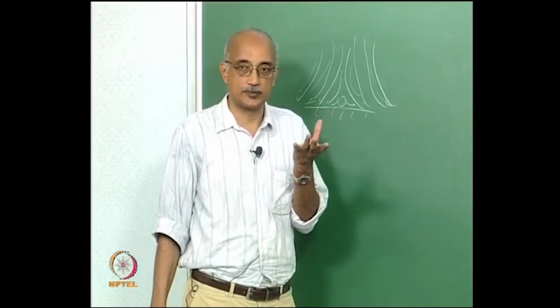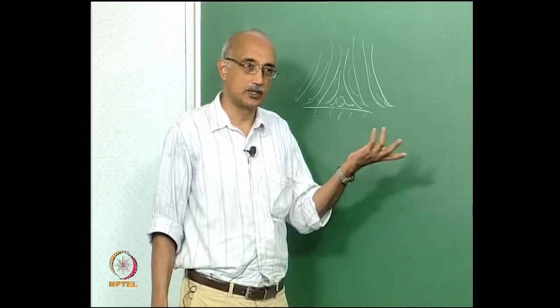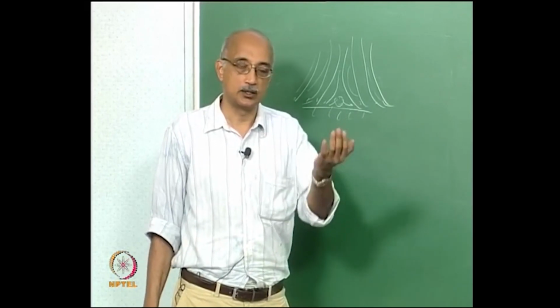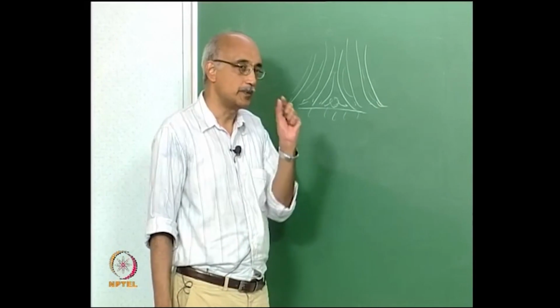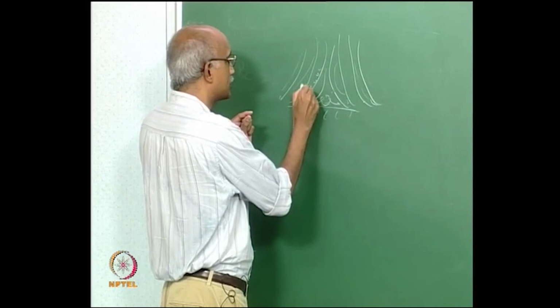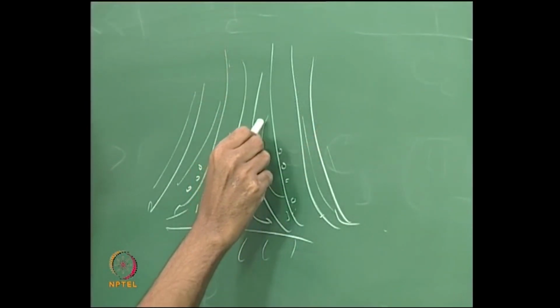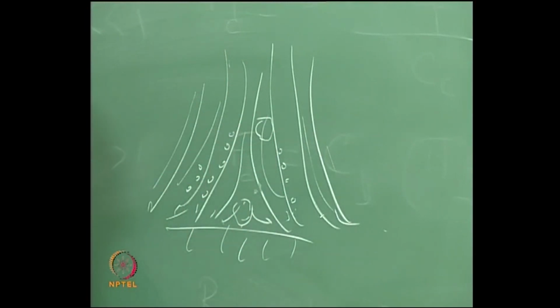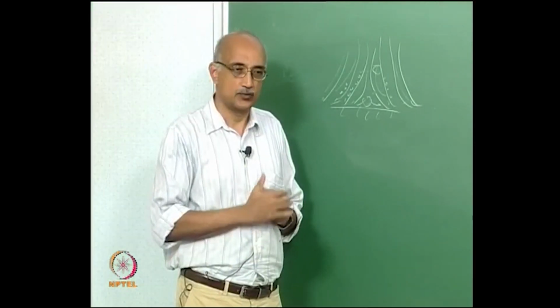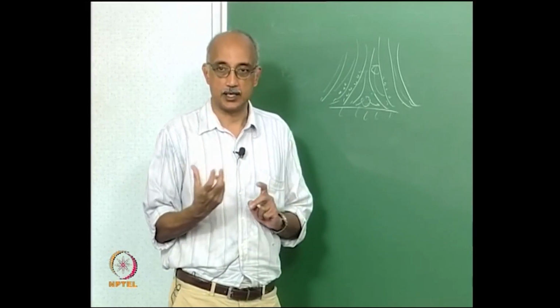Let us say the particle size gets bigger, gets to the nano sizes. What are they going to do? For the most part, they are going to do the same thing. They are going to keep following fluid streamlines. But as you keep increasing particle size, fine particles may follow the streamlines. But what if you have a particle that is this size? Is that also going to want to follow the streamline? No. It is going to want to separate itself from the fluid streamline and follow a different trajectory, and that is because of the inertia that it has.